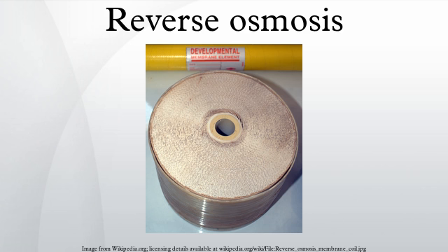The largest and most important application of reverse osmosis is the separation of pure water from seawater and brackish waters. Seawater or brackish water is pressurized against one surface of the membrane, causing transport of salt-depleted water across the membrane and emergence of potable drinking water from the low-pressure side. The membranes used for reverse osmosis have a dense layer in the polymer matrix, either the skin of an asymmetric membrane or an interfacially polymerized layer within a thin film composite membrane, where the separation occurs.